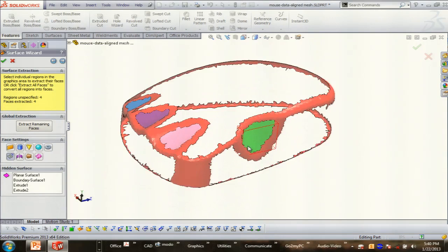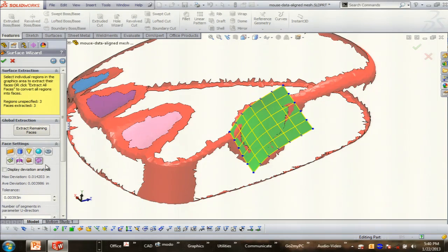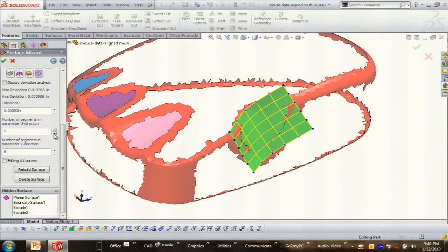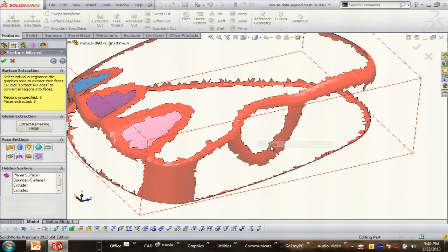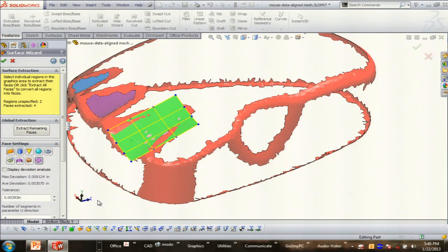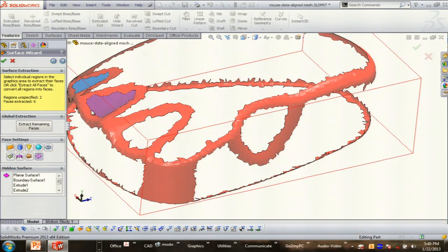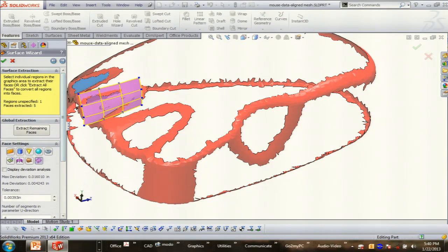And now all I have left are these other surfaces, and I think they're basically just B-spline surfaces. So I'm just going to do that. I'm going to take the mesh, the UV sections way down. And it remembers your last setting too. So when I do that, and I hide it, and I go on to the next one, like this one, it remembers that setting. So that's what I'm going to do. I'm going to take that one, hide it, and I'll just keep going. So that one, I don't have to hide them, by the way, at this point.